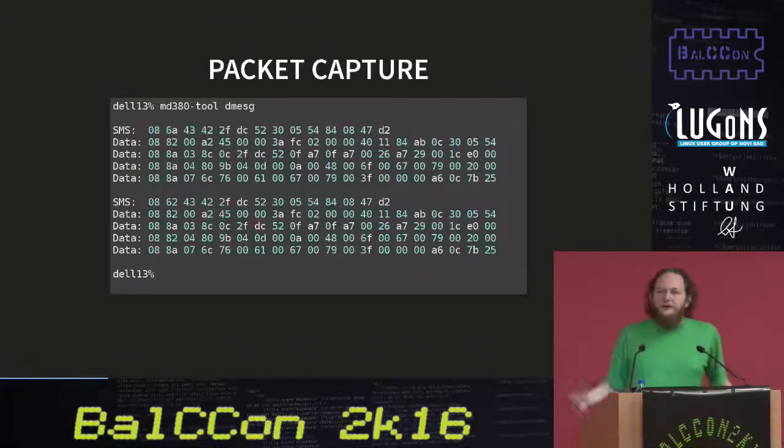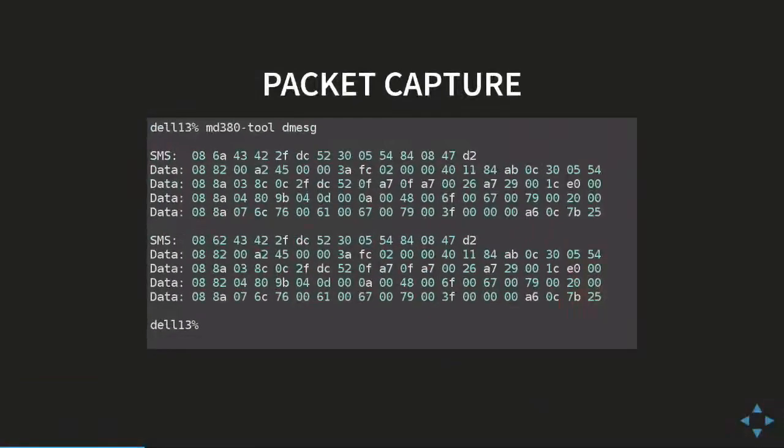So as part of my reverse engineering, I wanted to figure out how to capture packets for it. There was no packet sniffing hardware available when I began this project. So I wrote a series of Python scripts combined with firmware patches that allow you to do things like dump text messages. So this is a text message that I sent from one radio to another. And the contents of it is ASCII with a couple of accent marks. So it's 16-bit wide ASCII instead of 8-bit wide ASCII.